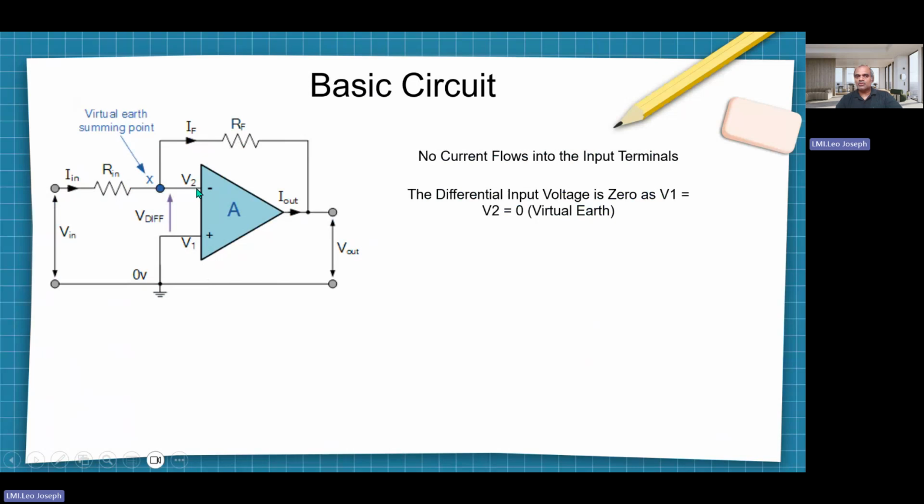This thing you have to realize. That is where this operational amplifier plays a vital role. So why is this current not going here? The operational amplifier generally has a very high input impedance. So due to this input impedance, the current is unable to overcome it and flow into this negative terminal. So it takes the opposite path and passes through the RF side like this.